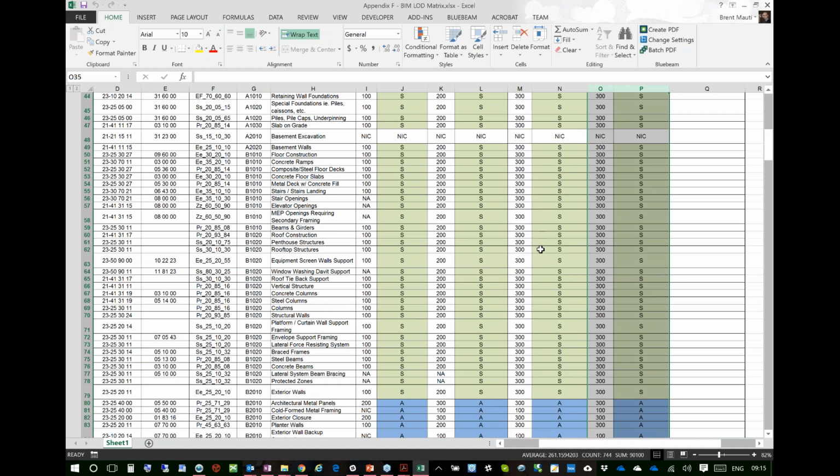We're not going to go and model the connection joints and the bolts and the weld points and all that stuff. That's LOD 400. I have a door that increased in size, so we increased the door. We have walls that became thicker, so we make the walls thicker. I'm not going to worry about the concrete rebars. That's usually just detailing work, and then it may be rebar models on the contractor side, but unless that was part of the scope of services of the structural engineer, they're not going to go and model the rebar.